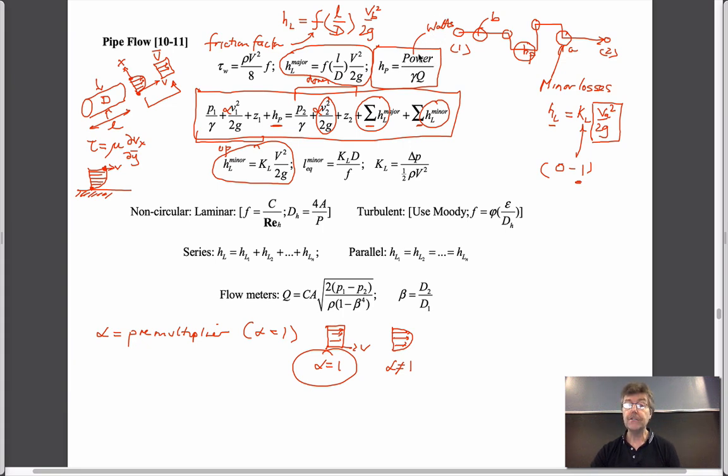And so the power you have to supply in a pump to give a given mass flow rate, so this is flow rate, equals average velocity times area. And unit weight would be the density of the fluid, multiplied by gravity. Natural gas probably isn't a gas at the pressures you pump it at in these pipelines. And so we could calculate that, and that's the basic expression that we will use.